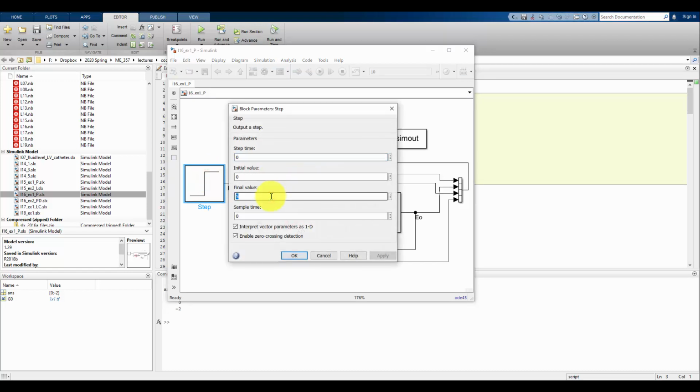The amplitude of it really doesn't matter because the max overshoot is a percentage. The amplitude doesn't determine what the rise time or the peak time is. But I'm just going to stick with an amplitude 5 for right now. If we change that, it's really not going to impact our analysis at all. It will impact the peak value of the input, but not the output of our system otherwise.